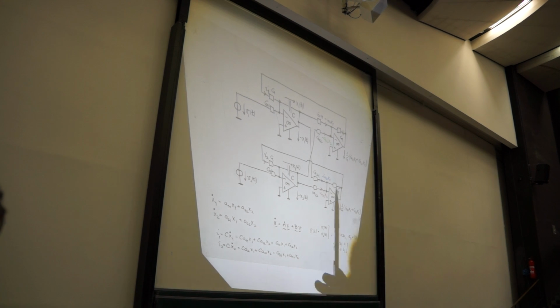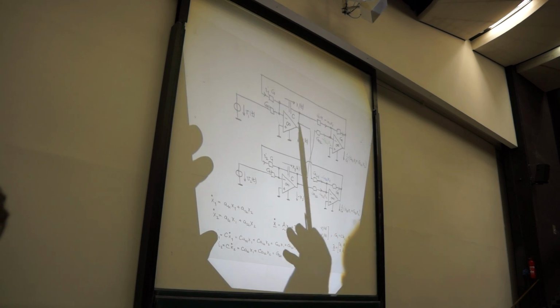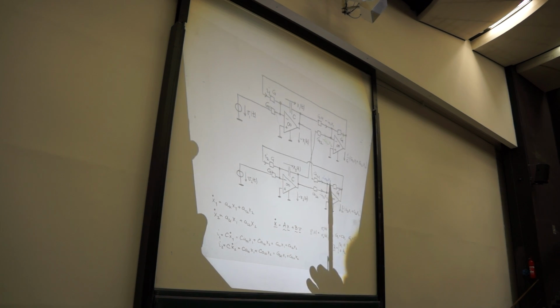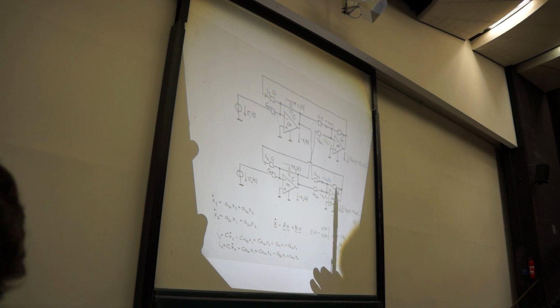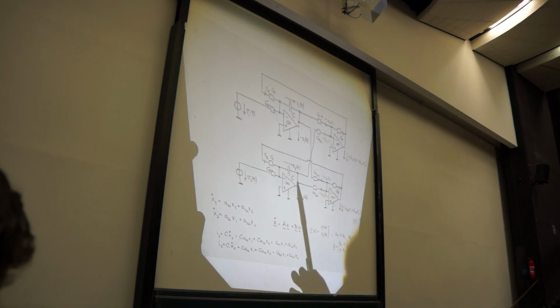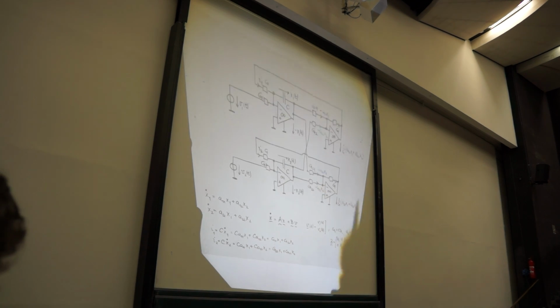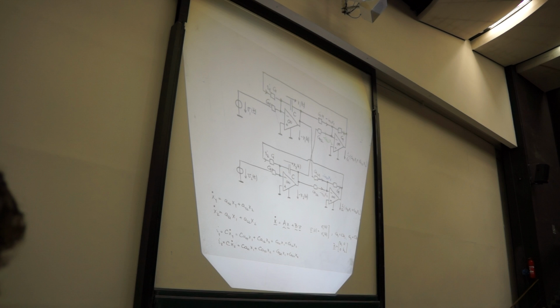And we do the same down here. From X1 we have a conductance G12 to that virtual ground, with a current flowing through that conductance, the blue one, minus G12 times X1, which obviously goes into that conductance. Then from the second one we have the red contribution, and both add up and produce that voltage here.